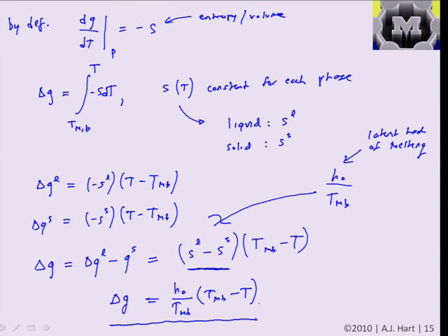Basically, based on how much favorable free energy change occurs due to melting because of the surfaces, that can pull the bulk melting point down by equaling with this energy change we are deriving here.